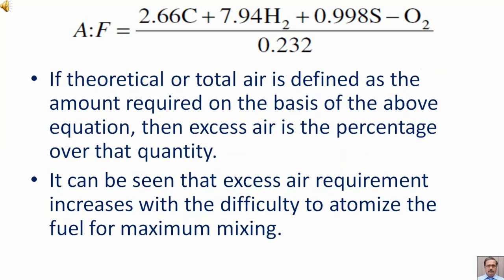If theoretical or total air is defined as the amount required on the basis of the above equation, then excess air is the percentage over that quantity. It can be seen that excess air requirement increases with the difficulty to atomize the fuel for maximum mixing.